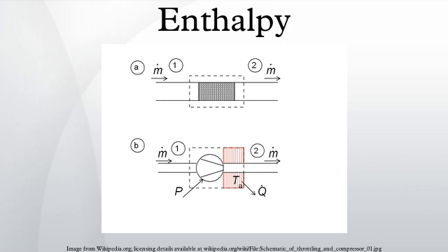Since the enthalpy is an extensive parameter, the enthalpy in F is equal to the enthalpy in G multiplied with the liquid fraction in F plus the enthalpy in H multiplied with the gas fraction in F. So, with numbers, 100 equals x_F times 28 plus (1 minus x_F) times 230, so x_F equals 0.64. This means that the mass fraction of the liquid in the liquid-gas mixture that leaves the throttling valve is 64%.